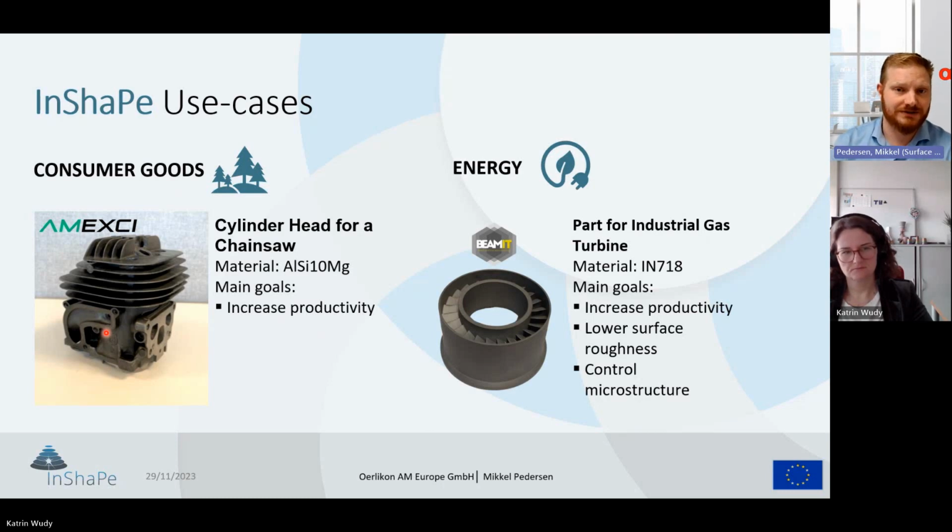So really fill up the build chamber with a whole bunch of these cylinder heads. To do this, again, we have to manage the residual stresses to avoid that they distort. And of course, minimize the amount of support structure that's needed, because we cannot connect every single part to either the part below or even the base plate, because the amount of post-processing we would end up with would be enormous. So again, similar points of how do we improve the print productivity? There's an element in the process itself and an element in what material we have to print around it.